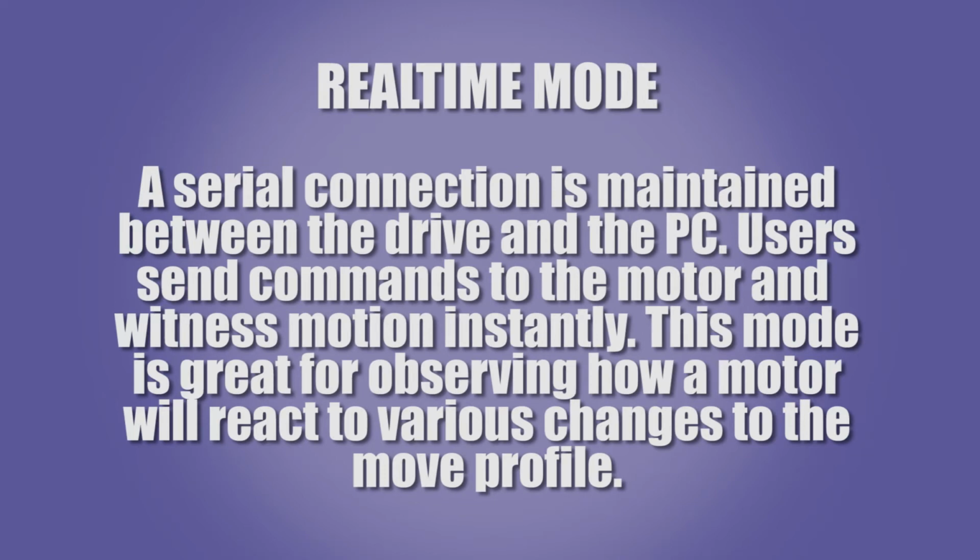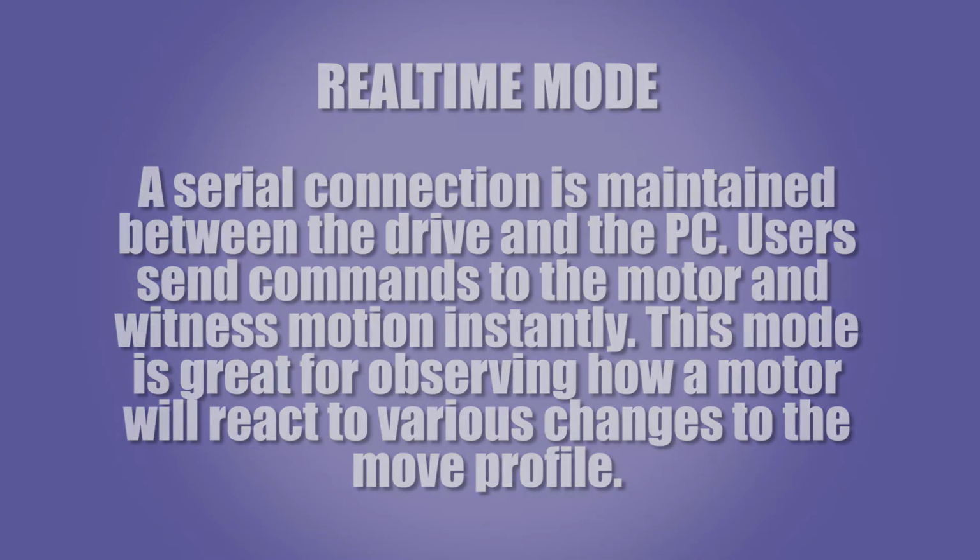Users have two ways of controlling the drive, either in real-time or program mode. In real-time mode, a serial connection is maintained between the drive and the PC. Users send commands to the motor and witness motion instantly. This mode is great for observing how a motor will react when various parameters within the move profile are modified.